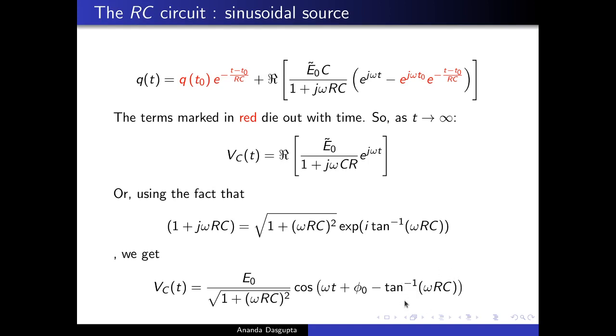You need a slightly bigger value of t to compensate for this negative term which is sitting here. So the input sinusoid, of course, keeps on going up and down, reaching a peak, hitting the trough, and going up and down again. The same behavior is seen for the capacitor voltage, but at a slightly later time. You need t to be slightly bigger for this to happen. So this is what we mean when we say the capacitor voltage lags behind the input voltage. In other words, if the phase shift is negative like this, you have a lag. If for some other circuit you have a positive phase shift, that will be a lead. That means, if this term had been positive instead of negative, you would have needed slightly smaller values of t to hit the same values of phase. So the peak and the trough would have come a bit earlier. So in this case, our terminology is that the capacitor voltage lags behind the input.